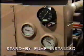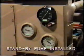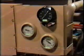A decrease in seal oil pressure will be alarmed, and the operator must take immediate action to rectify the situation. Usually a standby seal oil pump is installed, and in addition to this, a DC emergency pump is provided in case of loss of AC auxiliary power.